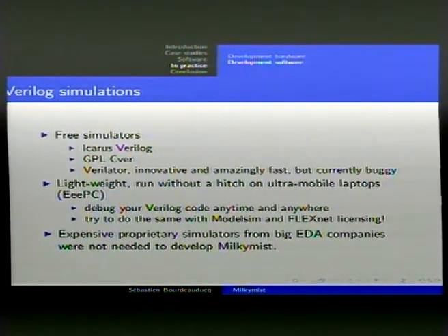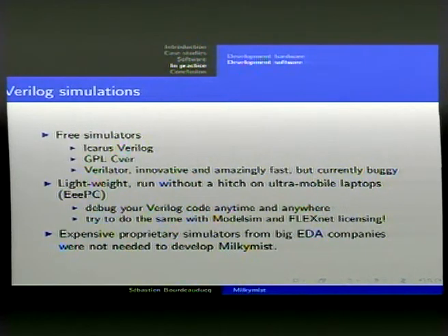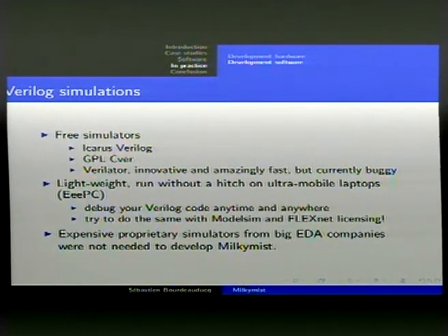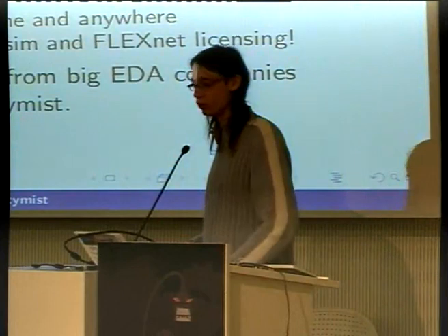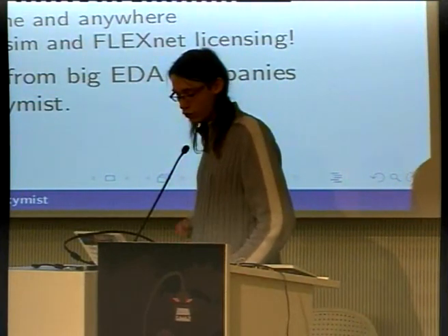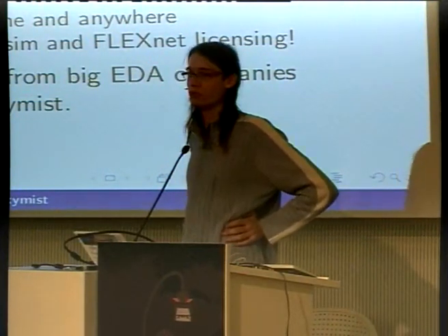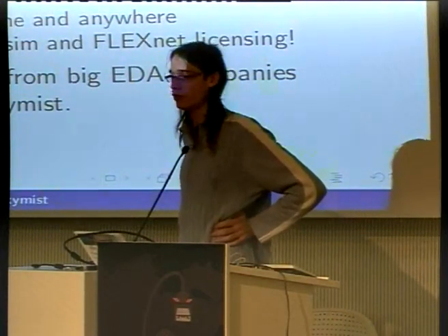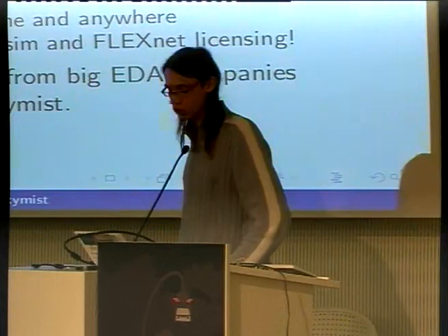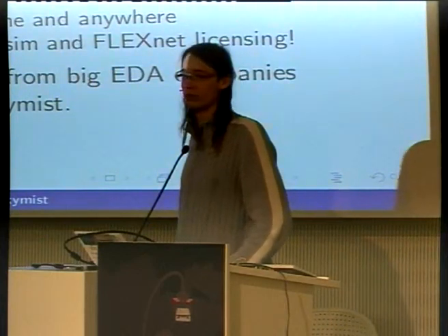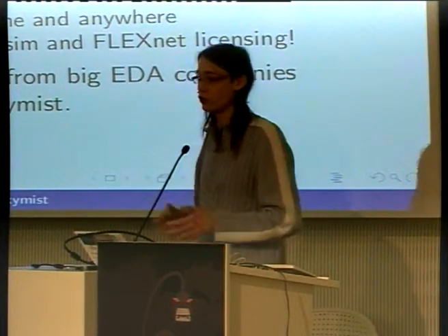And you definitely need simulations on this system. First, to explore the cache size that I have shown, you needed simulations, because you will not increase the cache size as you want in the hardware. And also for debugging, because debugging such a complex system is very complicated. And if you are not able to see what's happening inside the design, you can just forget about debugging anything, because you will just put it into the FPGA, and it will not work.